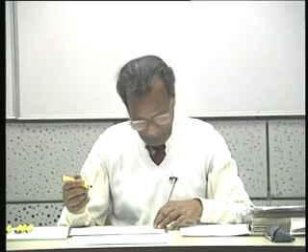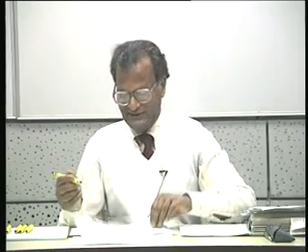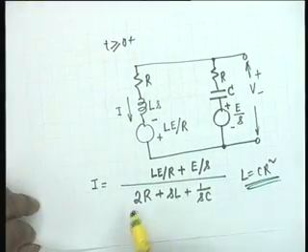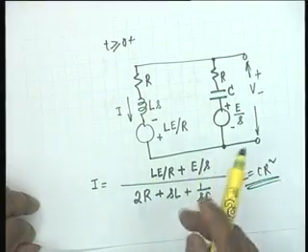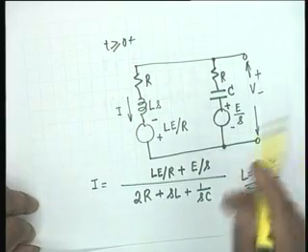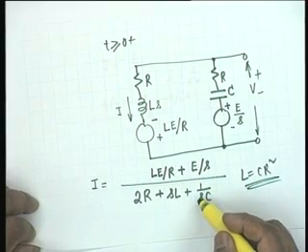Shouldn't it be 1 over S plus 1 over CR square? Because the denominator in the term for I is a quadratic thing. So yes, it will have one pole only. That cancels with one of the zeros. You see, this is what I say. This special value of L makes the numerator factor, the linear factor, cancel with one of the linear factors in the denominator.